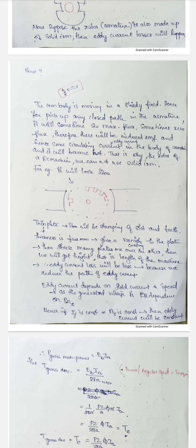If you are stacking together all these laminated plates to a height, then that becomes the length of the armature. So you have to imagine it in such a way; maybe in a later session I can show you a picture of that. Alright, so you have to stack it in such a fashion that all the teeth become aligned. All the slots become aligned so that you can get a longer slot. Okay, and it is screwed.